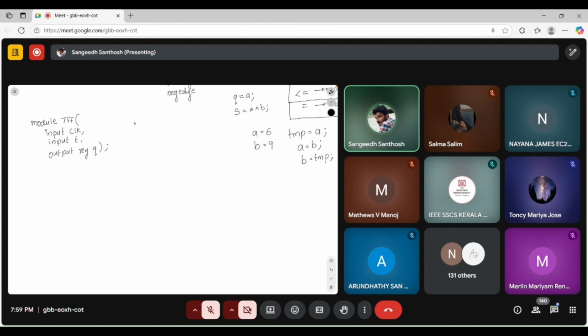Usually, I go with this part because when we have more than 50-60 signals, we will be forgetting to mention them in the port list, and we will be directly declaring them as input or output. So in this case, we will be mentioning only one time. We don't need to define that again. Okay, so try to design with this.